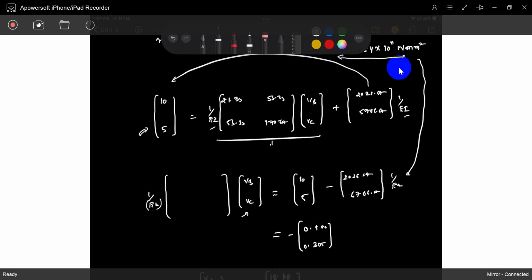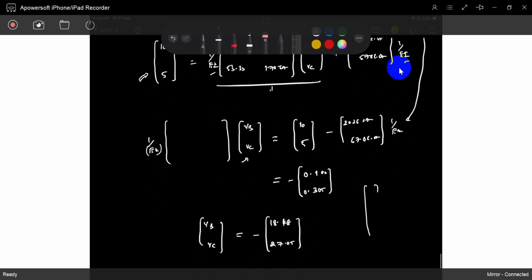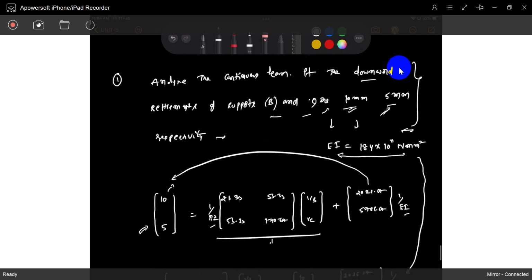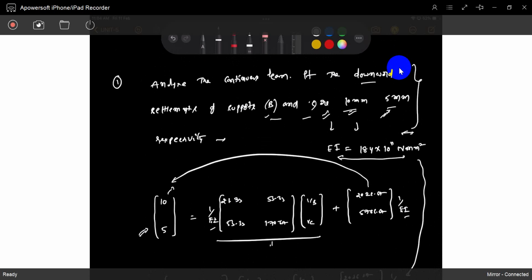Understood? Otherwise, how is it, sir? If you take the matrix method also, these are the final matrices, and this is the 6 by 6 matrix plus these are the fixed force vector, right? So here we eliminate those two. Here those two are not 0, 0. We just equate this vector and this vector to this vector. Every time these two are zeros only, we will get those unknown forces. Previously we saw it. Here these final settlements are fixed values.